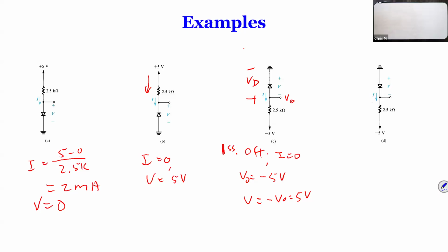See, in this case, you can say VD is -5, right? So that's reverse biasing. So it depends on how you mark the symbols. You shouldn't confuse, because what you're looking at is whether the voltage is positive on the triangle side or on the flat side.